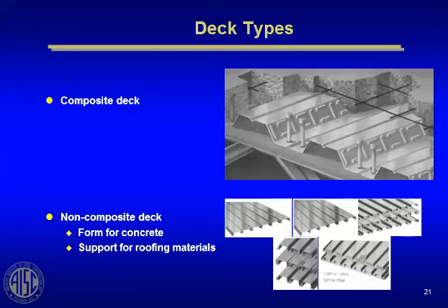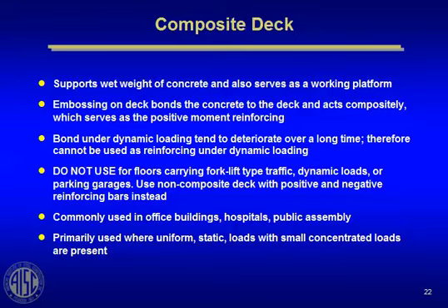Composite deck, I think we covered pretty well. Most of this is a repeat of what we already talked about. Just remember that under dynamic loading like forklifts or heavy vibratory equipment, you probably don't want to count on that composite deck as the positive moment reinforcing. You would want to reinforce it just like you would a normal concrete slab for flexural resistance.